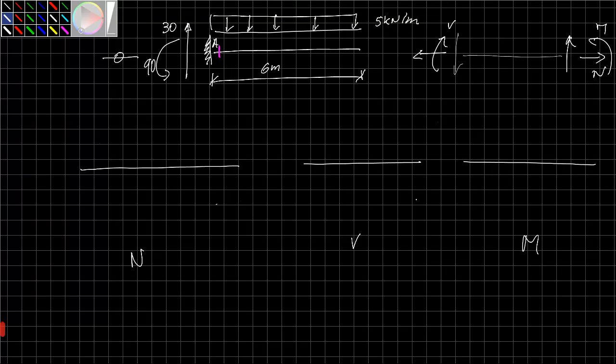If I look at axial force, so forces parallel to the bar, to the left of this section in pink, I have no forces parallel to the bar. So the axial force here is 0. If I look to the left at the green sections, the sum of all forces to the left parallel to the bar is still 0, which means the axial load is 0 and 0 and 0. This is actually true for any section I choose. So the axial force is actually equal to 0, so there's no actual axial force.